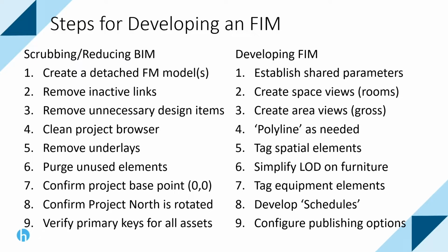You'll have to make sure everything is tagged properly so that you can review it and read it. You may want to simplify three-dimensional objects, or simplify what we call level of detail, for things like furniture. You don't need three-dimensional furniture in BIM or in a facilities information model. You can get away with 2 dimensions, for example. You want to tag equipment elements, and you can even develop what we call schedules in Revit.